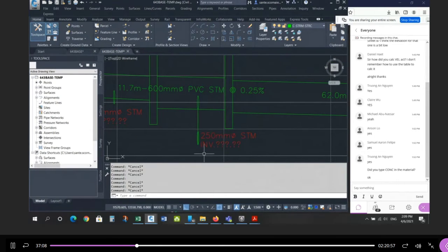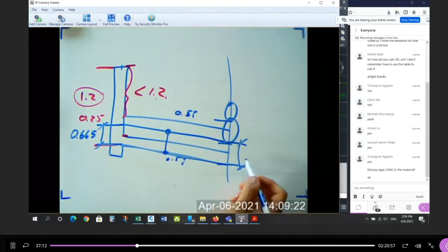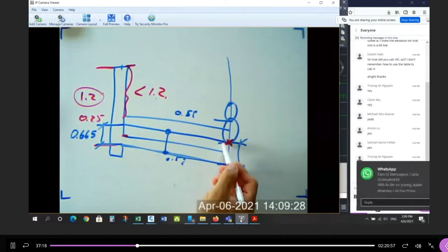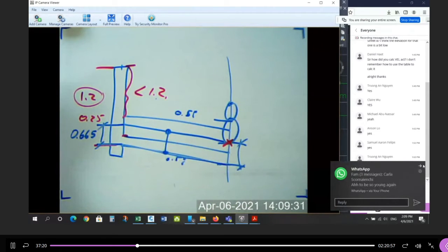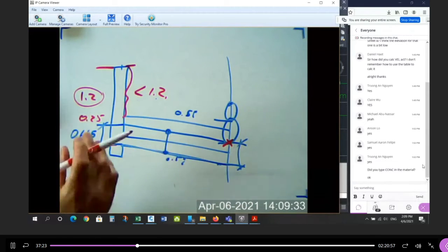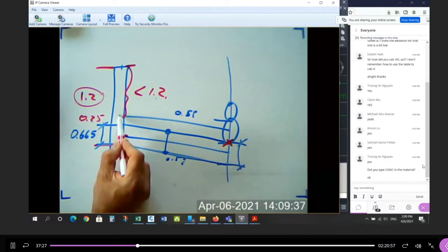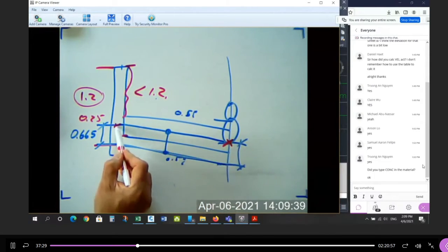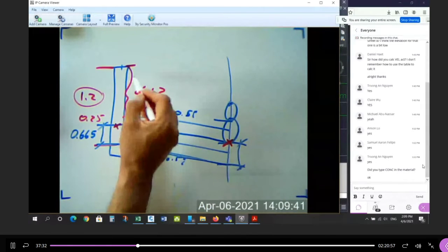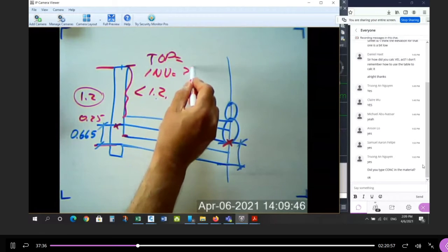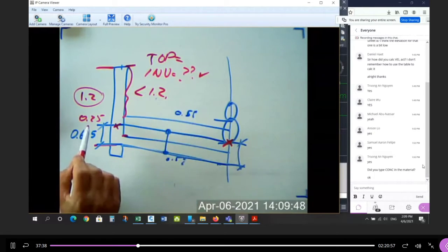So now what do you do? Now you start at the main line. Now you design. Now you know the elevation here. Let me use a different color. Now you know the elevation here. You're going to go up 0.5%, and you're going to recalculate the invert inside the pipe. And now you have the top. That doesn't change. The invert in the structure, this changes. You have to update this number.